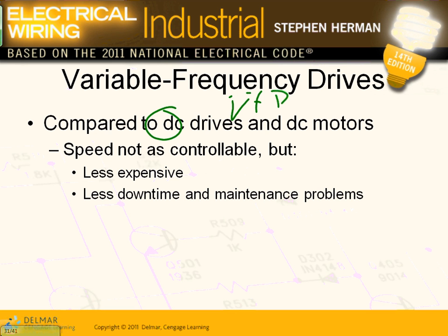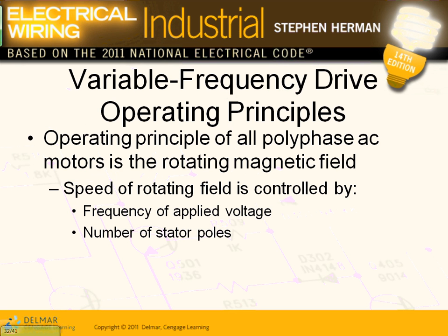When you have an AC drive, you're controlling with less maintenance than the DC motor and so forth. The most important thing is we are controlling the speed of an induction motor with a VFD. So DC drive goes with DC motor. DC motor is high maintenance, out the window, except for certain applications. Most of what you're going to have in the air handling unit right now is induction motor. With induction motor comes a VFD.